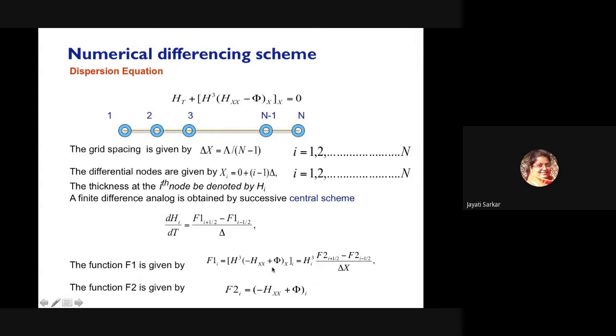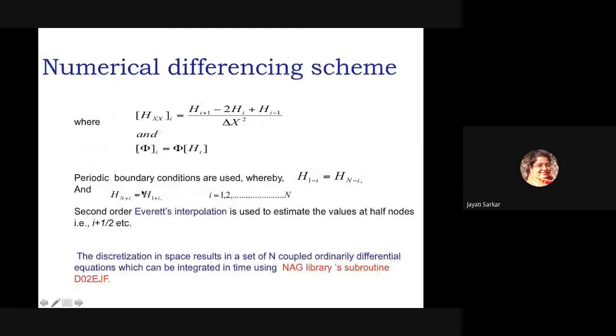And we can actually solve these equations. For boundary conditions, we mainly use periodic boundary conditions, because as I have told you, the length of the substrate can be infinite. So we don't do the entire domain, but a small portion of the domain, and we include periodic boundary conditions at the end. So you will get these thicknesses. You have to solve this for h at different spatial location points i, and at different times you need to evolve it.